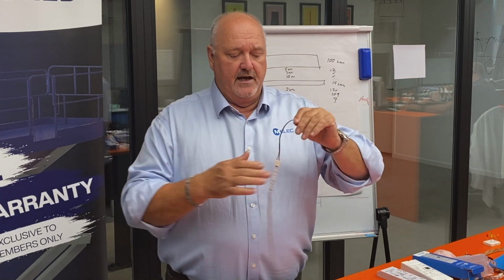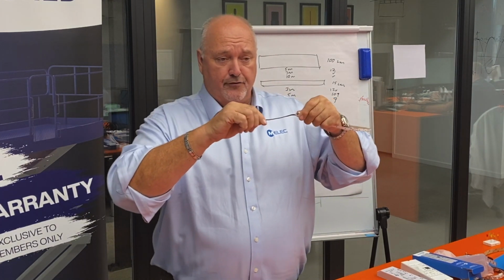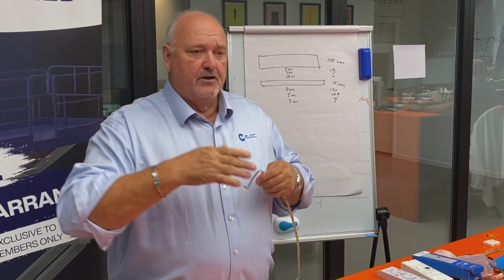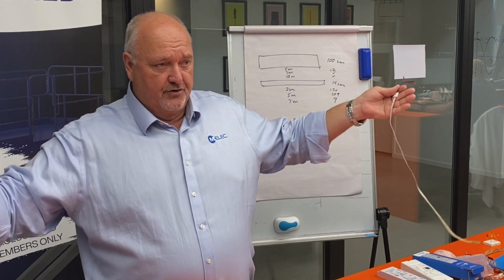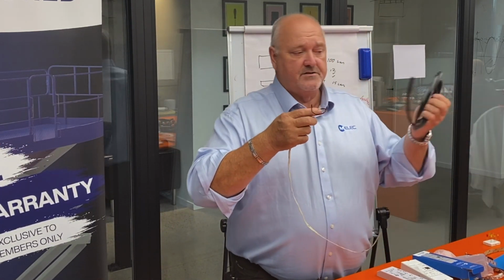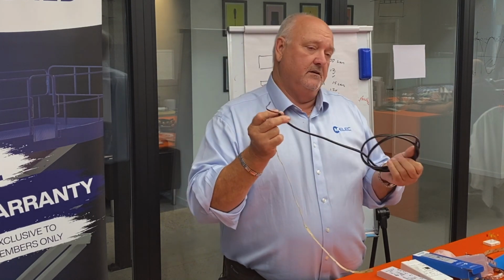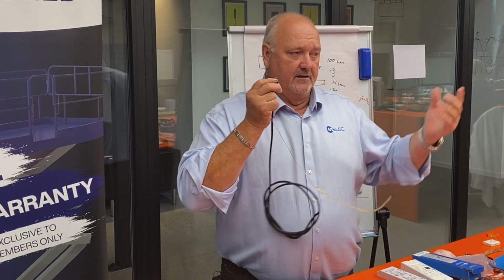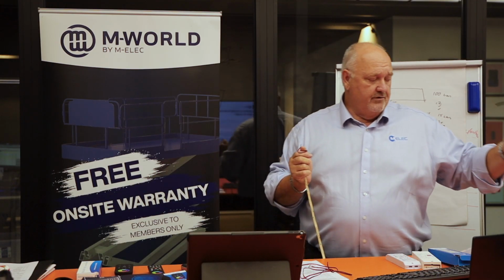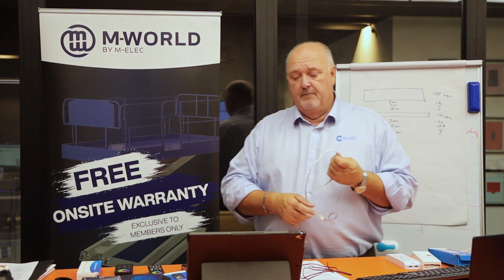So when you get LED strip, you'll get these little tails. They're about 150 mil long, attached. So if you have a large distance between the controller and the LED strip, keep the tail on, but attach a larger cable from that tail to where the controller is, and then a small bit of cable at the end, because it's going to carry the bulk of the load, and it'll reduce your voltage drop over that distance. Because what you do want to have at the end of the day is 12 volts at your strip, a good, clean, solid 12 volts.